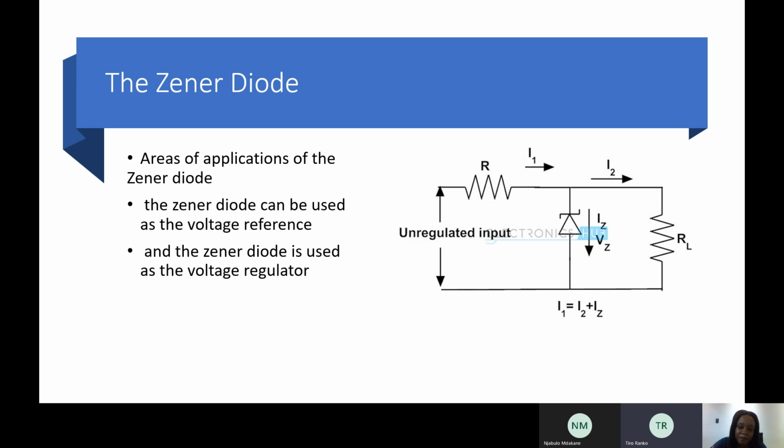Ma'am, when you said the resistor in parallel, why did you say the voltage is the same? Yes, because the rule is that when we have components in parallel, the voltages are the same. The current is the part that splits because there are two paths. So the voltage remains the same. In series, the voltages split. Did I answer you? You understand? Yes, ma'am. Okay, that's good.